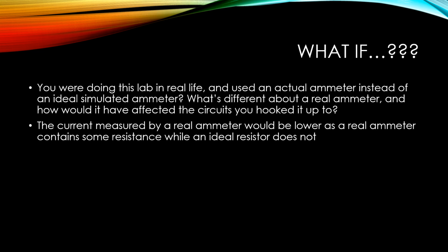What if we were doing this lab in real life and used an actual ammeter instead of an ideal simulated ammeter? What would be different about a real one? The current measured by a real ammeter would be lower, as a real ammeter contains some resistance, while an ideal one does not.